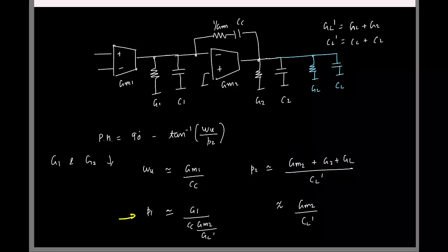Another couple of responses I found was, if you reduce G1, P1 is also going to reduce, so the phase margin will improve. But again, P1 is already at a much lower frequency, so the phase it contributes is almost 90 degrees, isn't it? So even if P1 reduces, it's okay. It will give the 90 degree phase at a much earlier frequency. At omega u, it's still 90. Again, mathematically speaking, that is also correct. Actually, it will not be 90 degrees; it will be 89.89 degrees. If it reduces, it will become 89.899 degrees.